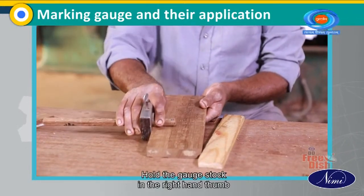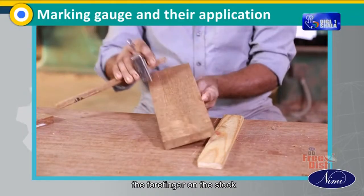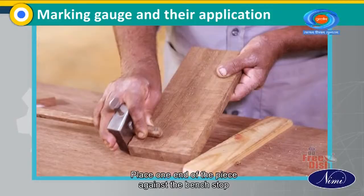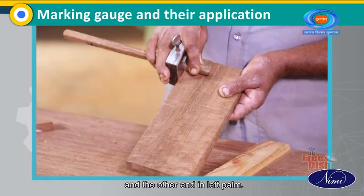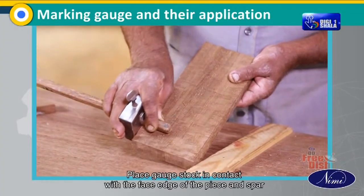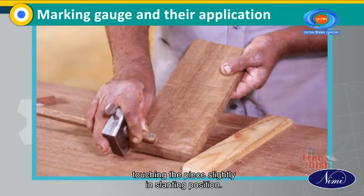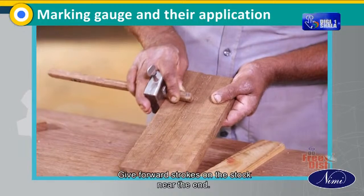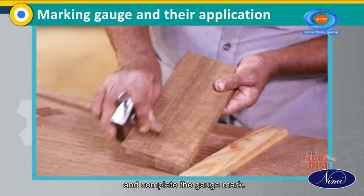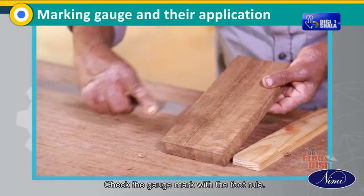Hold the gauge stock in the right hand, thumb on the top behind the spur, the forefinger on the stock and the 3 other fingers on the stem of the tool. Place one end of the piece against the bench stop and the other end in left palm. Place gauge stock in contact with the face edge of the piece and spur touching the piece lightly in slanting position. Give forward strokes on the stock near the end. Hold the piece in your left hand and complete the gauge mark. Check the gauge mark with the foot rule.